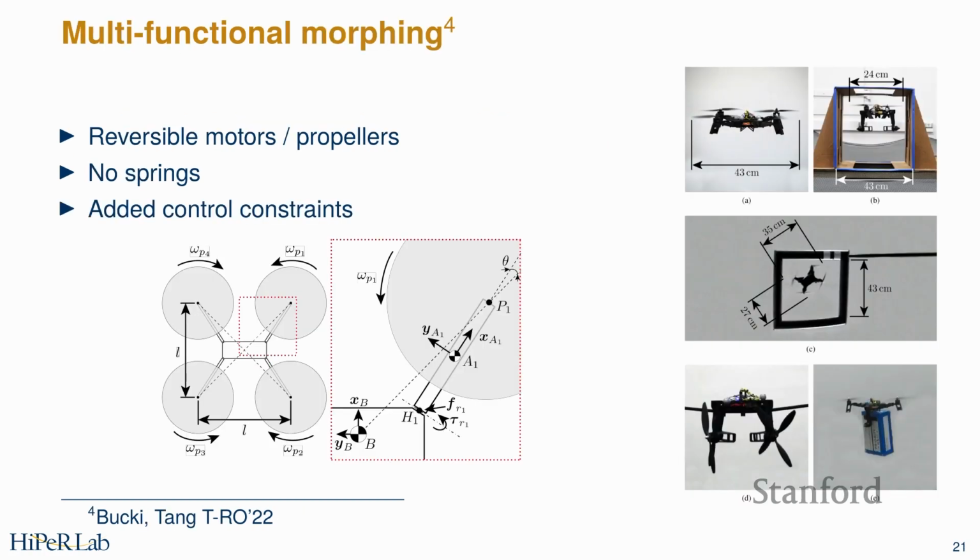The way we ended up doing this, the second iteration, the nicer design, looks like this. We have 4 arms. Each of these arms has at the end a thruster, the propeller, with a hinge that allows it to fold 90 degrees up or down. There's a mechanical stop on each end of this. The propellers are bidirectional, so you can imagine if you anchored the body and the propeller pushes up, you'll extend. If you reverse thrust, you'll push down.